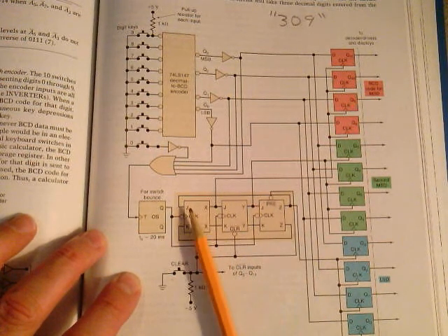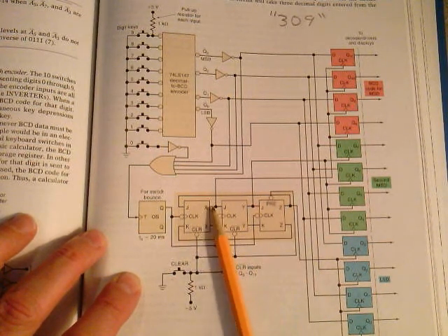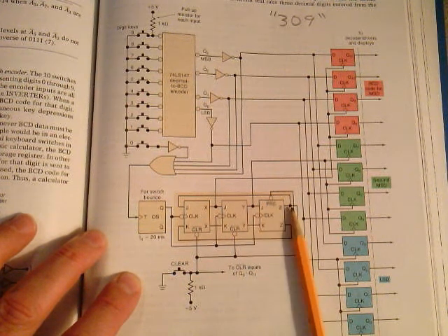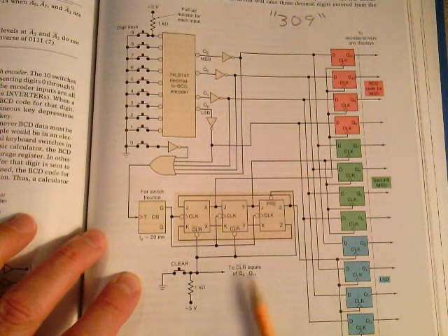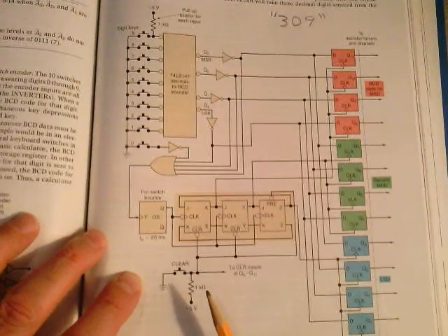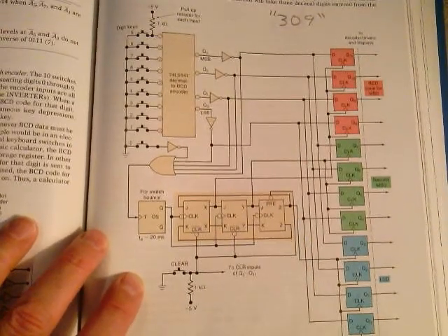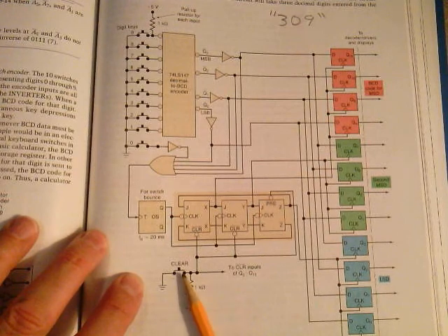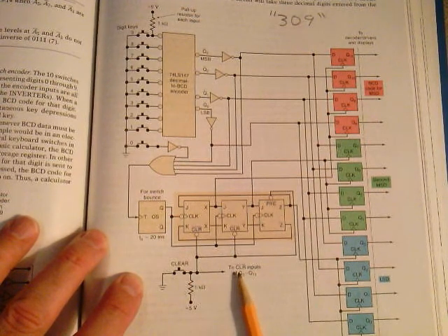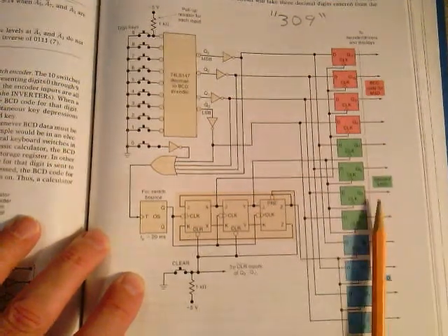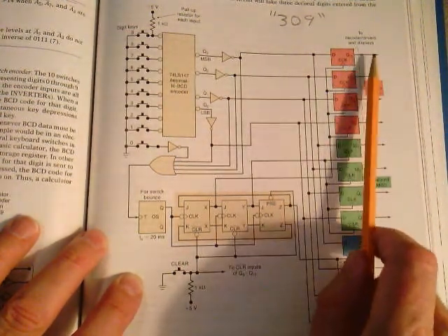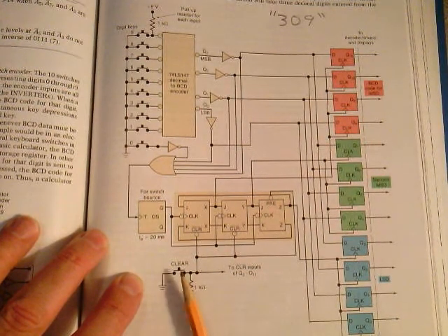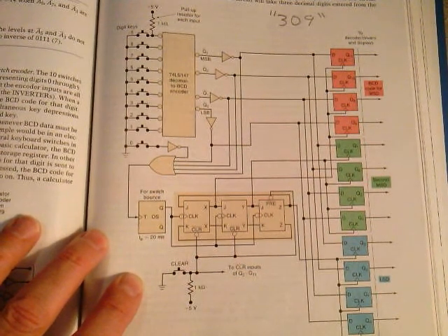So you set up your ring counter as a 0, 0, 1. Similar to the way you'd have done this on a previous quiz. I'm pretty sure I asked you to put this type of circuitry in to set up the initial 1 condition. Notice it also goes low when you push this button, and it clears all these flip-flops. You end up with zeros the whole way down through all 12 of these outputs, Q0 through Q11, all 0. Then you release that button. Now you're ready to enter the digits.